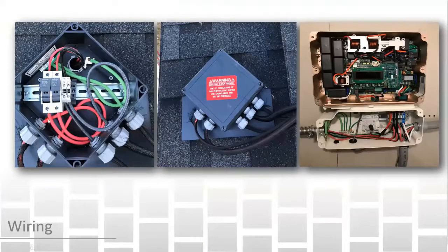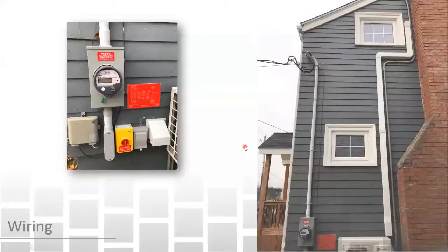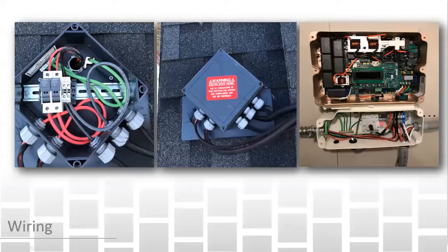So this is a DC power optimized system. I've got my two positive DC wires coming into my fuse holder, and they are fused to the size of the wire, in this case, number 10, 30 amp. I've got my terminal block for my negatives, and then I've got my bond and ground coming up. Cover goes on, rodent guard goes across over those individual conductors, and then I wire up my inverter here.